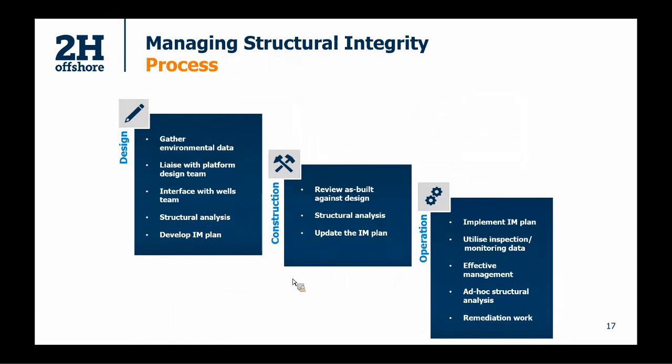So what is the process for managing the structural integrity? Well, the first stage is to consider the conductor as a priority at the design, construction and operational stages. So a lot of the time we find that the platforms are already designed and have been finalized before the conductor is considered. So it's useful to have some flexibility in the platform design when the conductor is still being considered, because you may find that if you move a guide by half a meter or a meter, you could be making an order of magnitude difference to your fatigue life. So it's worth making sure that the design, not just of the conductor, but of the platform, gives you the kind of optimum system that you could have.